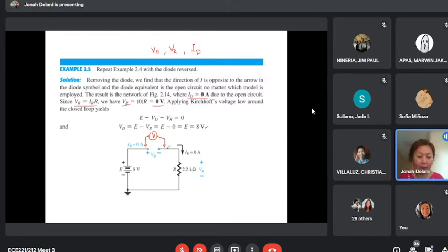So if we see, for example, a power line that is cut, it has no current. But the moment you touch it, it may be live and there is voltage. Although actually there is no current, the moment you touch it, you provide a connection for the current to flow. So isolate or insulate it, and do not touch. Especially if you see it on the road, it may be live. So if you see a cut wire hanging, do not touch it. You would provide a connection for the current to flow.